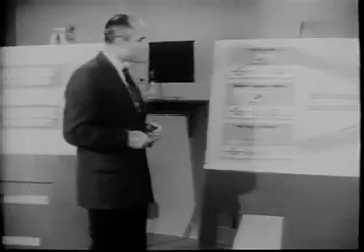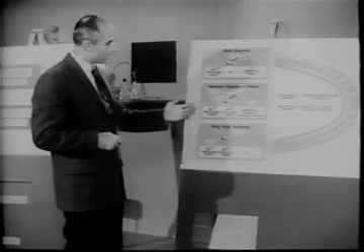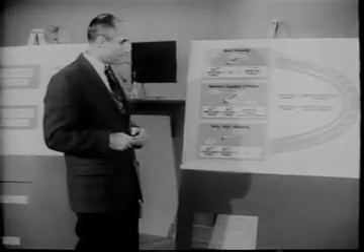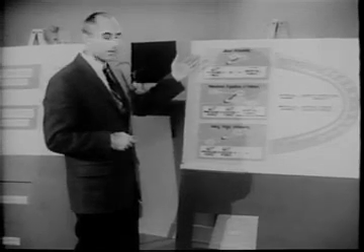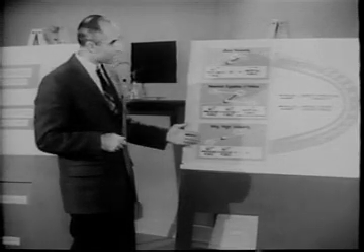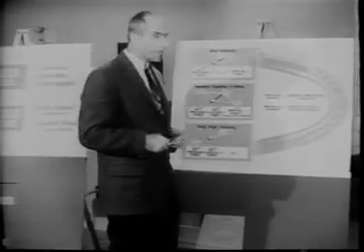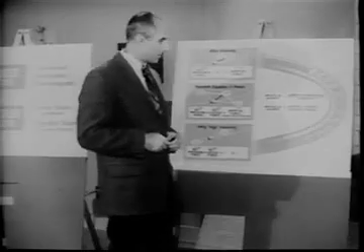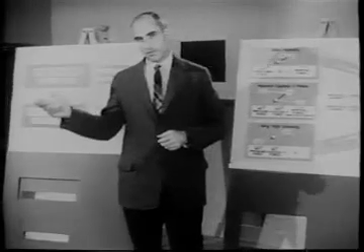Then, by thinking about two extreme cases, fluids of very small viscosity and fluids of very large viscosity, we were led to a most useful idea, the Reynolds number, which allows us to categorize the type of flow in terms of the relative importance of viscosity. Finally, we recognize that the drag on an object, like the forces on a fluid particle, could be divided into two parts, pressure drag and viscous drag. This set of ideas is a powerful tool for interpreting and explaining experimental observations.